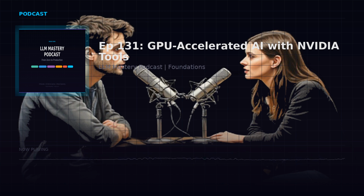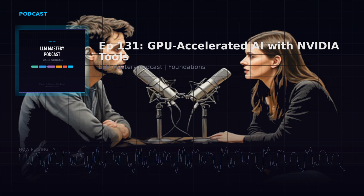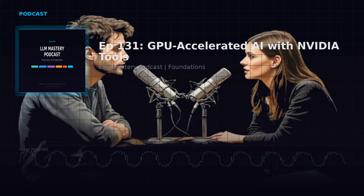Okay, so if the GPU is this massive army of thousands of workers calculating in parallel, you would naturally think that making an AI faster just means giving them more math capability, right? That's the logical assumption. Add more workers, get faster math. Exactly. But the source material points out that for large language models, inference, the act of actually generating the response, is typically not compute bound at all. It is memory bandwidth bound. Yeah, this is the big plot twist. The GPU can actually perform the matrix calculations much, much faster than it can physically read the model's weights out of the memory chips. Wait, so it's literally just a massive traffic jam.